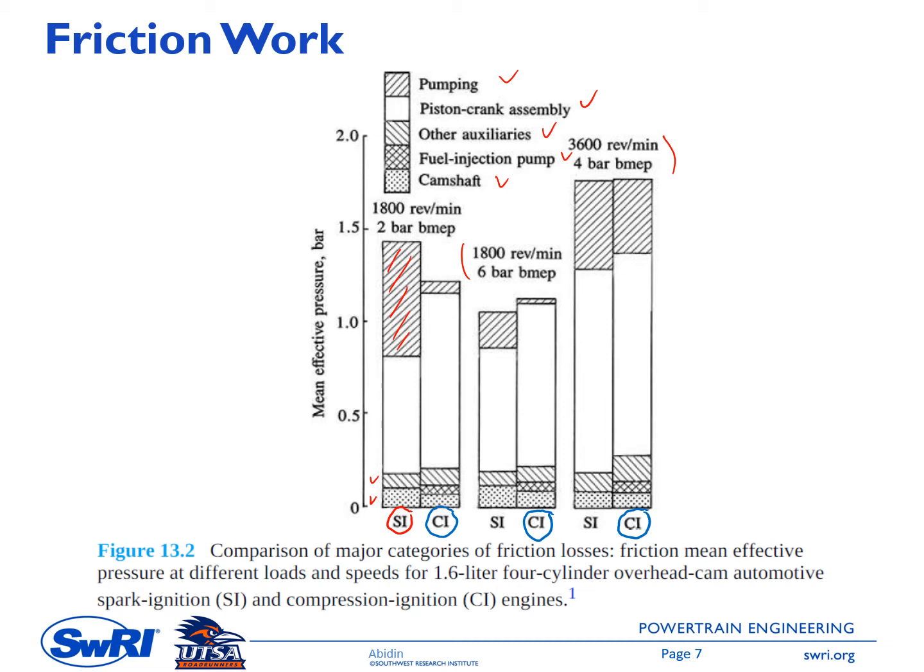An important characteristic of this turbocharged engine is that, as you can see in here, the losses due to pumping are much smaller if you compare with the SI. So as we increase the engine load, it will be smaller, and at some point it will be positive. So it means it will disappear completely.